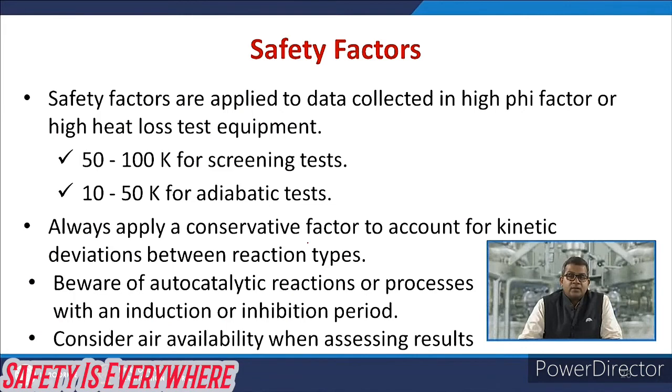Now let us have a look at various safety factors. Safety factors are applied for these runaway reactions to collect data in high phi-factor or high heat loss test equipment. Now 50 to 100 Kelvin for a screening test, 10 to 15 K for the adiabatic test. This is always applied as a conservative factor to account for kinetic deviation between the reaction types. Now one must beware of autocatalytic reactions or a process with an induction or inhibition period. You may also consider the availability of air while assessing the results.